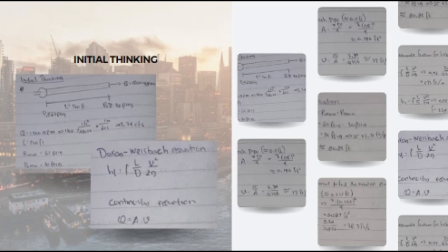and the data that the equation provides us is Q equal to 1,500 GPM. We convert to CFS and we get 3.34 CFS. So the length of the pipe is 500 feet. The pressure max, or P1, the pressure at discharge of the pump, is 65 psig, and the P2, or P min, is 30 psig.